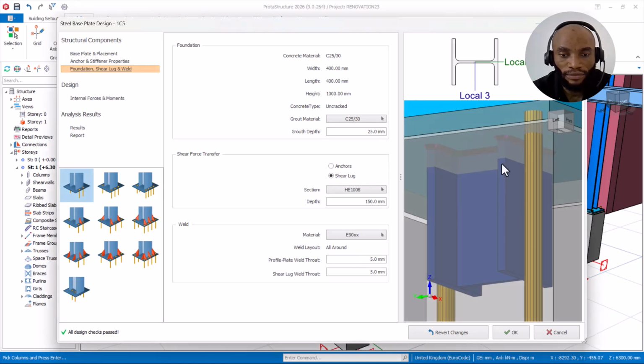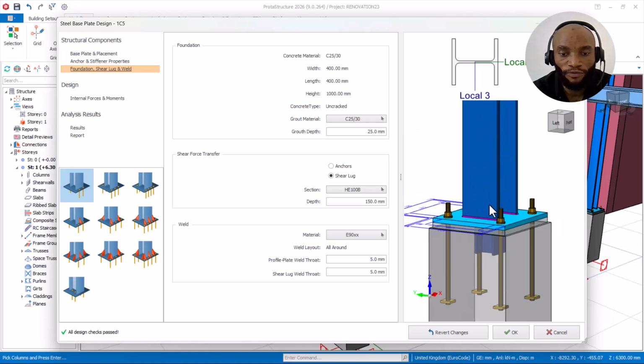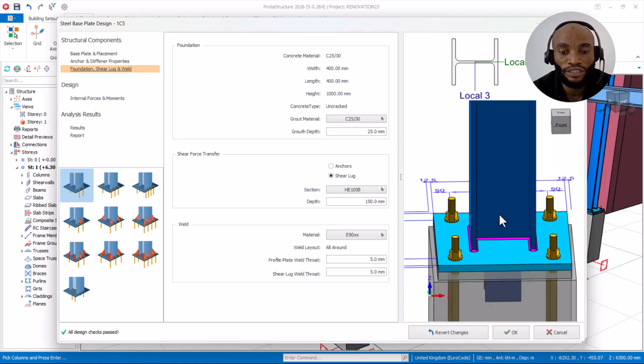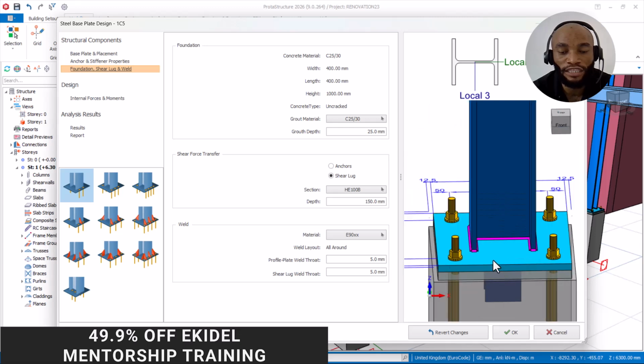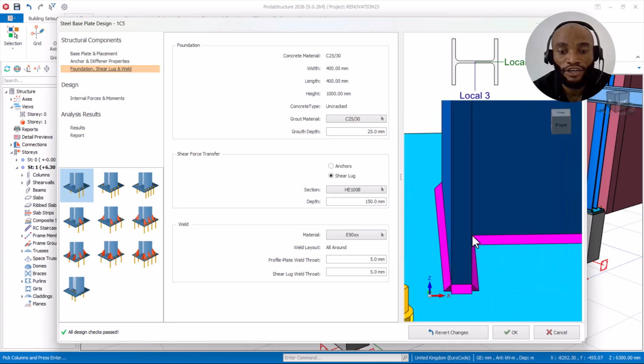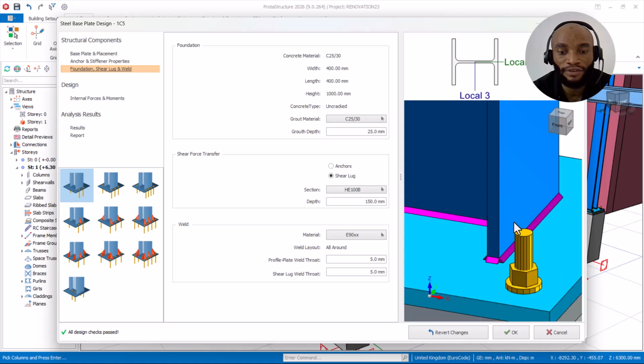Then, knowing this now, you have to check the thickness for the welding of the profile itself. The profile here is HEB 180, and the lowest thickness here is the web, which is 8.5 millimeter. The flange is 14 millimeter. So since the web is 8.5 millimeter, the flange is 14 and the base plate is 20, your welding thickness should not be more than the lowest thickness that is to be welded together. Along this now, you can see that we are going to weld the web and then the flange and everything. So in this case now, I will choose 8.5 as my welding thickness.